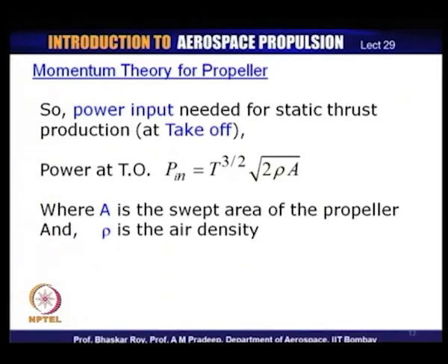Now, this power input is what the engine has to supply, and in some of the earlier lectures, we have seen that in most cases for aircraft operation, the input power during the takeoff is one of the highest powers, probably the highest power required during any phase of the aircraft flight. Which means the power required by the propeller would be about the highest, and that has to be supplied by the engine during the takeoff.